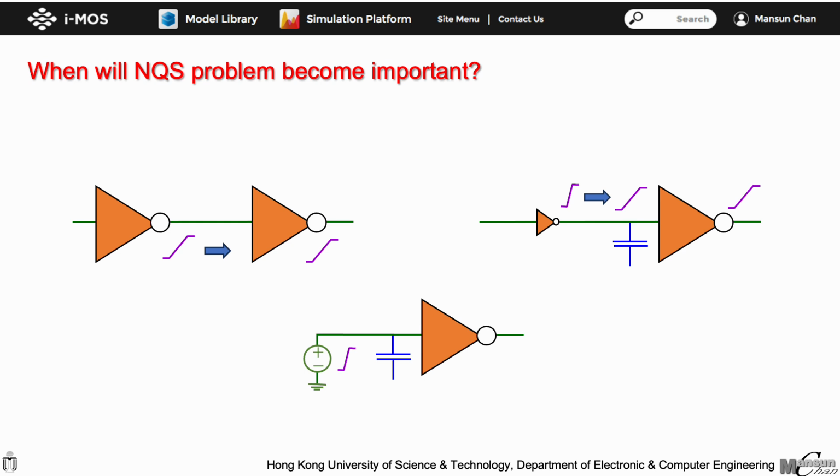To really demonstrate the problem, we have to use an ideal voltage source with almost a step function input to a transistor, which is not very realistic. Therefore, even though the formulation in Spice is incorrect, it can still be used to approximate most practical situations, as long as we are not operating a transistor near its cutoff frequency, at which the transistor fails to function.